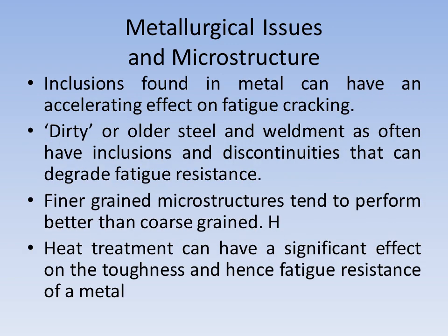Inclusions found in metal can have an accelerating effect on fatigue cracking. Dirty steel, older steel and weldments often have inclusions and discontinuities that can degrade fatigue resistance. Finer grained microstructures tend to perform better than coarse grained. Heat treatment can have a significant effect on the toughness and hence fatigue resistance of a metal. By heat treatment, the grains are refined.